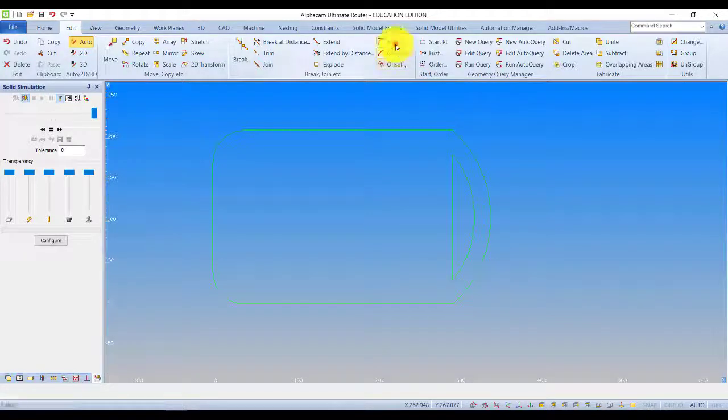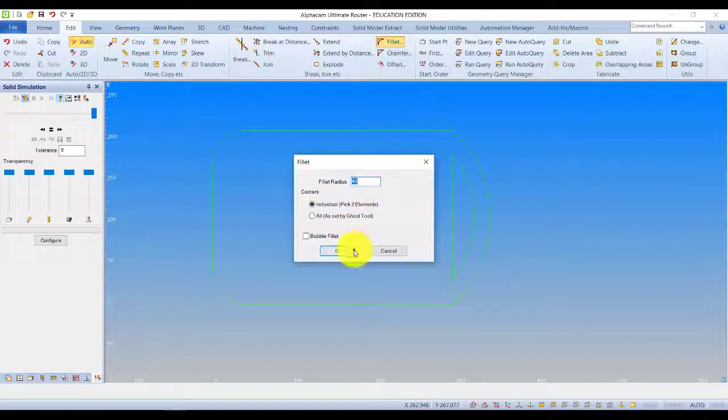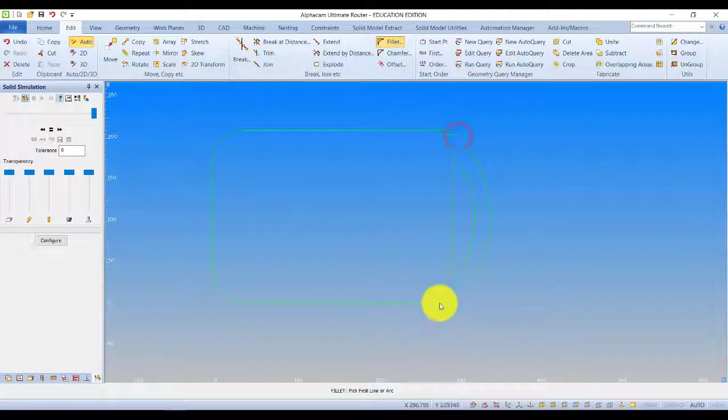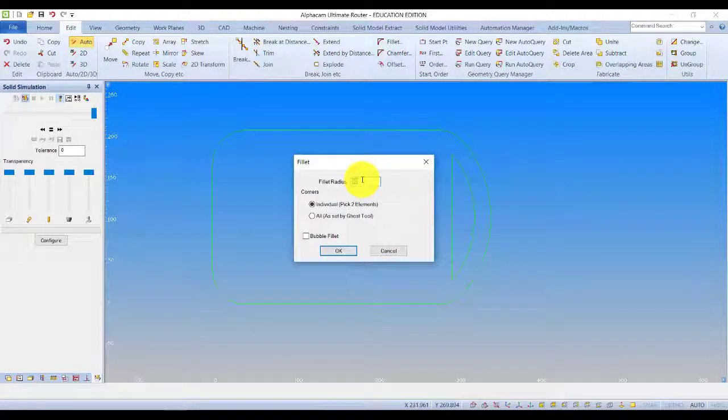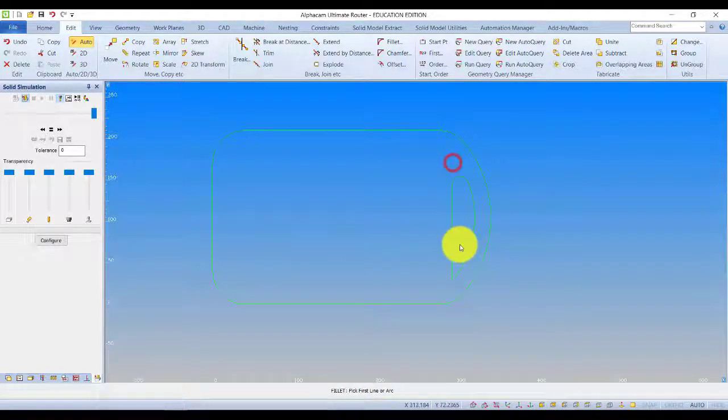And if I put another fillet on, I actually have the 40 loaded, so I'll put the 40mm fillet onto those corners now, seeing as I have it, and call back up the fillet and put in a radius of 10mm. Press OK. I can now fillet the 2 sharp points of that handle and give me the shape of the handle that I'm after. And let me just see how I'm getting on there. Pretty good.